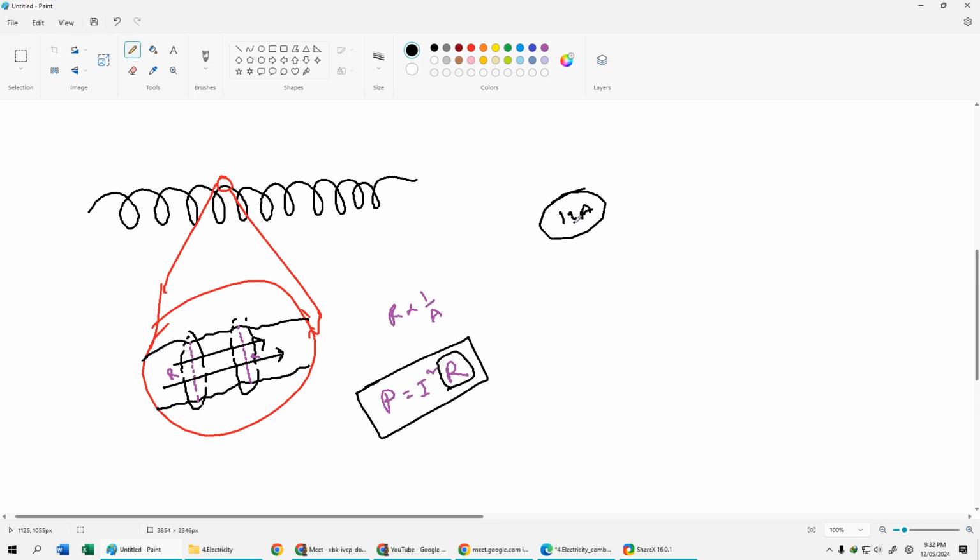So if we did not have the variable resistor, let's say if we did not have the variable resistor and we turned up the switch at room temperature giving all the voltage, the current might as well be 100 ampere for all I care, right? So 100 ampere of current would be extremely large to produce a huge amount of heat over a small section. The rate of heat production would be so high that those portions of smaller cross sectional area would not have enough time to dissipate it out to the neighboring region. As a result, that coil might break.